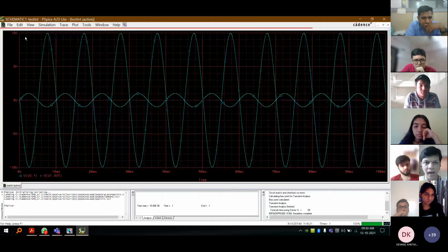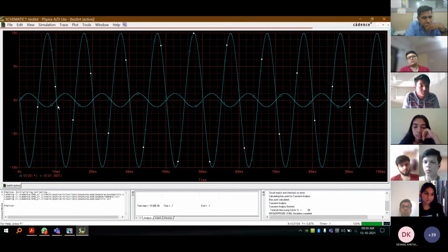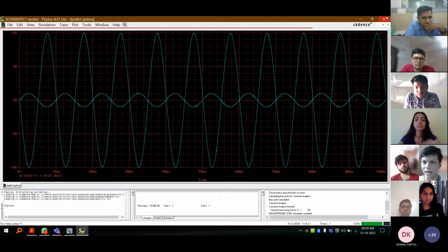There we go. So we have pretty much 10 volts. If I go into the nitty gritty, it'll probably be 9 point something, but you can see it as 10 volts up here. And you can see that we still have our 1-volt peak to peak. So here we're getting the ideal gain of a normal op-amp. The op-amp is not working as an integrator here, right?